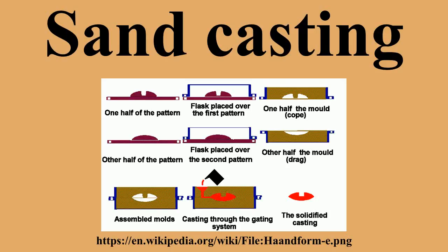Design requirements. The part to be made and its pattern must be designed to accommodate each stage of the process, as it must be possible to remove the pattern without disturbing the molding sand and to have proper locations to receive and position the cores. A slight taper, known as draft, must be used on surfaces perpendicular to the parting line in order to be able to remove the pattern from the mold. This requirement also applies to cores, as they must be removed from the core box in which they are formed.